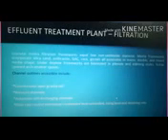Media systems include silica sand, anthracite, GAC, rock and garnet, all available in mono, dual, and mixed media form. Underdrain systems are fabricated in plenum and lateral styles, incorporating open arc strainer nozzles. Filter designs available include conventional open gravity cell, pressure filters, and automatic self-discharging filters, and filter rate control techniques include level control, rising level and declining rate.